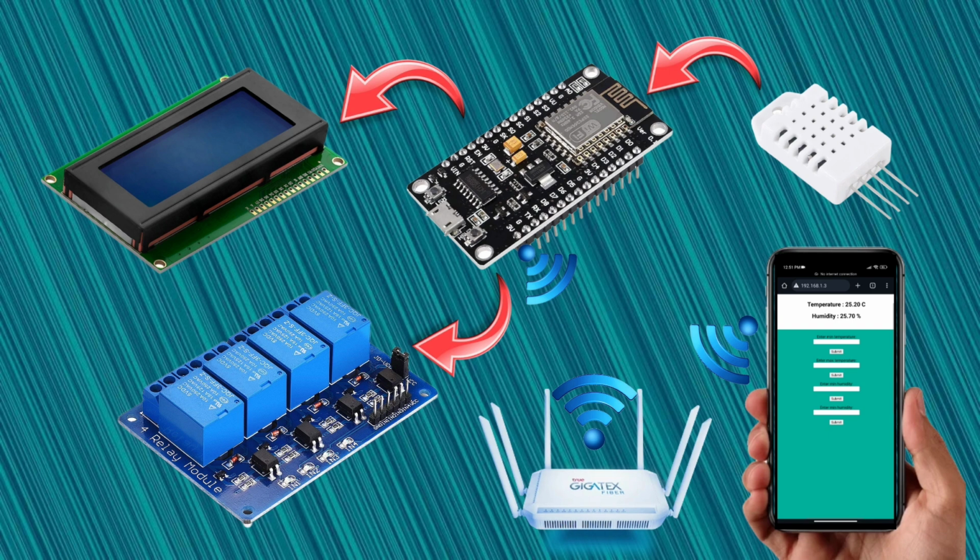Additionally, the Wi-Fi module connects to a Wi-Fi modem or a mobile hotspot via a local network. You can enter the module's IP address in a browser connected to the same network and access the module's user panel to send minimum and maximum temperature and humidity values.